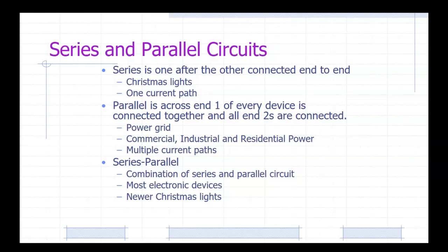Basically you're wired series parallel to the Alabama Power. It's series because if the transformer goes out at one end, your whole street's done until somebody comes out and fixes it. However, if, let's say, somebody burned out all the bulbs in their house and they're down and out, does that mean anything to the rest of the street? No. So there's series in the fact that all our power comes from single poles. Parallel in the fact that we pull it individually from that pole.